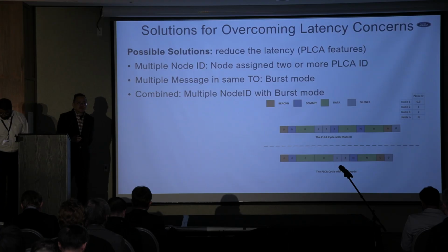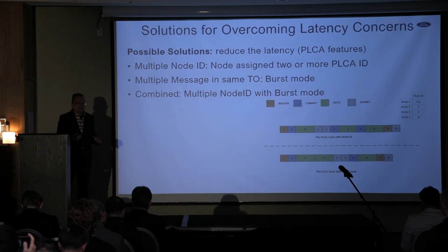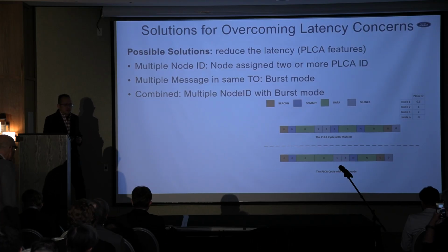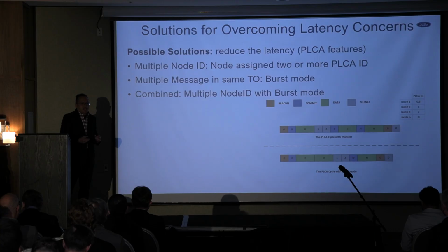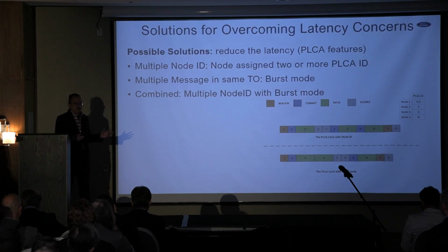Yeah, so we want to quickly go back. We want to use the PLCA, and we use the 10BASE-T1S, because the 10BASE-T1S is between CAN FD and Ethernet. They also have the multi-drop. It's good to use on the zonal networking. They can also use Ethernet, like the 7 layer, so they can use multiple protocols and provide the application to use. They can also guarantee, using the PLCA, that each node has an opportunity to send a message.